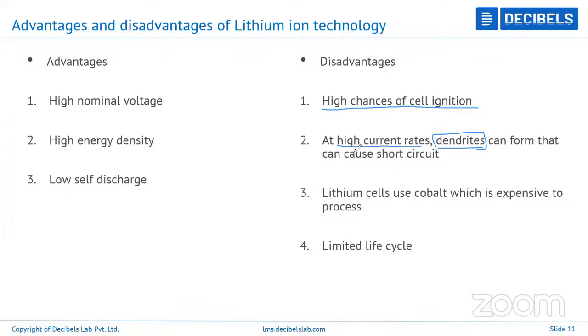So that serves as one of the major drawbacks. Another thing is expense. It uses cobalt, which is a bit expensive to obtain. It's a bit expensive to mine, and a bit expensive to process and finally manufacture as well, in terms of lithium ion applications. When it comes to EV applications, obviously you want to keep the cost down. So cost per kilowatt hour, you want to keep the value low, and to do that you have to use a lower amount of cobalt. Basically, cobalt itself makes the entire lithium ion cell pretty expensive. Generally, lithium ion cells are kind of expensive.